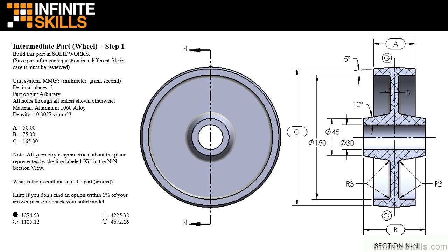The only items I would not include in the sketch profile is the fillets. My practice is to add the fillets as features and add them last in the feature manager tree. So let's go to SolidWorks and create this part.